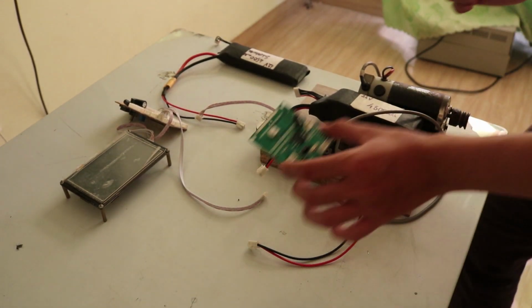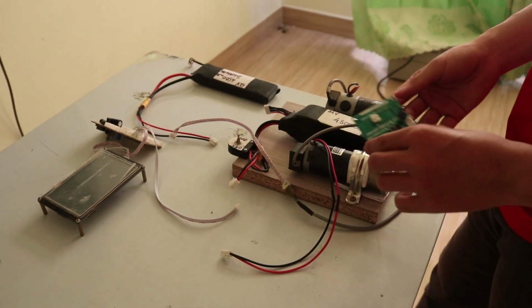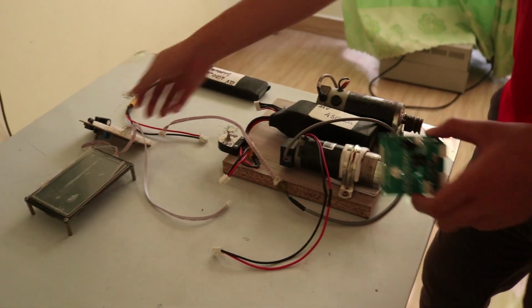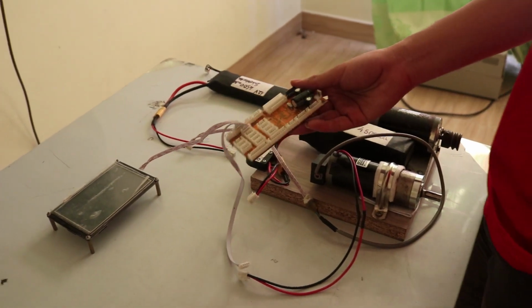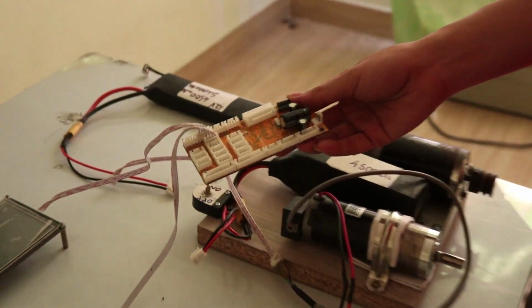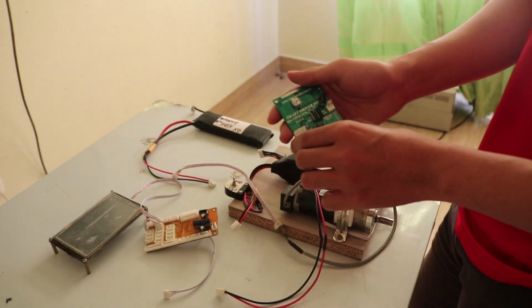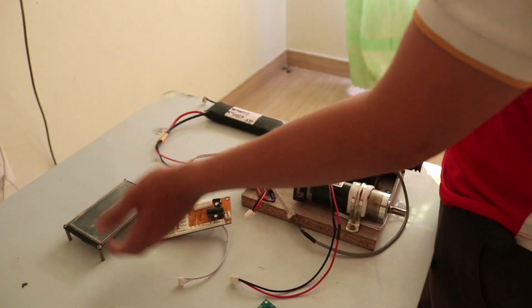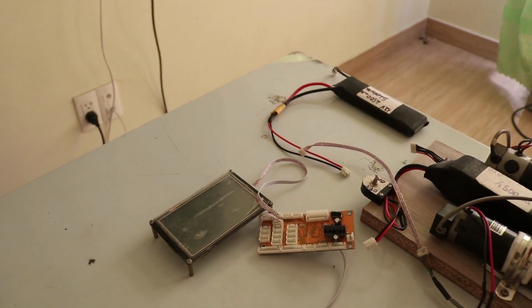I'll run a demo of the PID position, one direction and one pulse mode. In this mode, I use an STM32F4 mainboard to generate the PWM pulse, which is the control signal that we put in the control part of the driver. The mainboard is controlled by an HMI to generate the control signal as I wish.